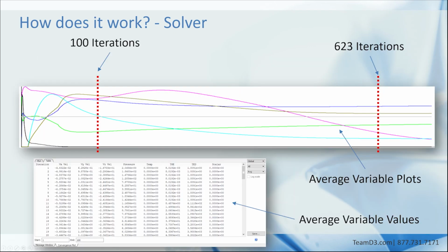Solving these nonlinear equations is an iterative process. There are many variables involved, and they are dependent on each other. There are too many unknowns to find a single explicit answer. So the solution is dialed in to a point where error is acceptable. This involves initial guesses on physical values at the beginning of the analysis and assessment of the resulting physical values after the analysis to determine if they adhere to physical laws. Results of one iteration serve as input into successive iterations, the goal being to reduce the error between the actual result and a physically balanced result.